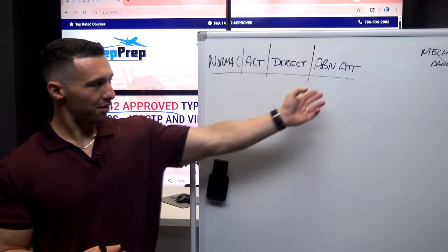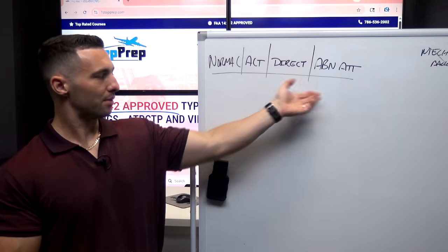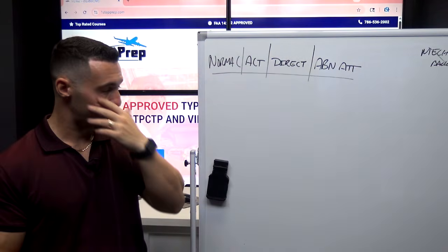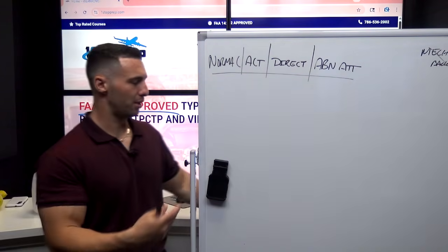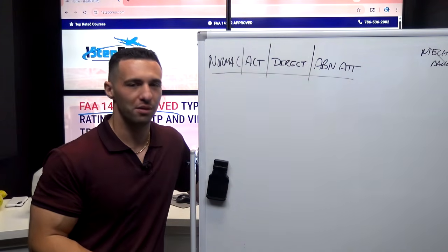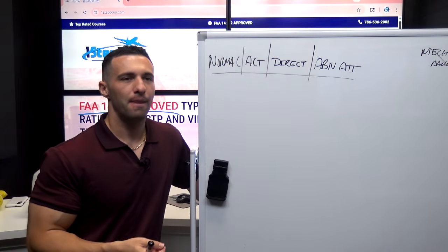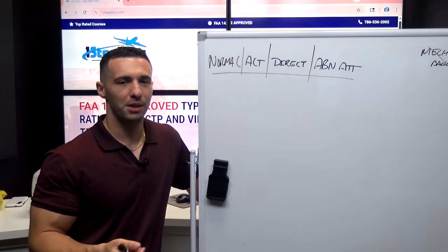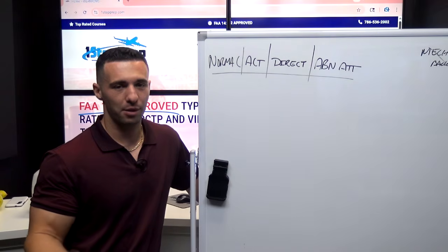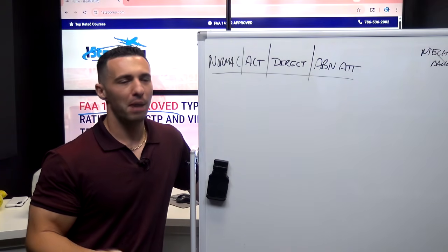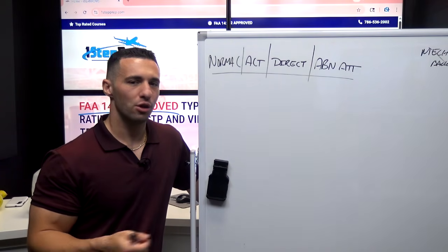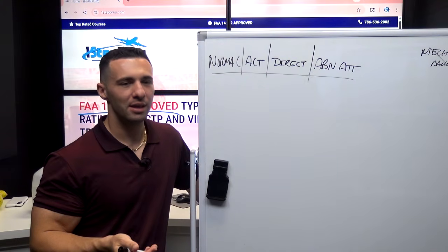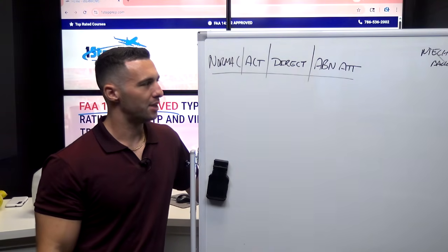This is one of these laws. Now, I guess a lot of these decayed or degraded laws, or maybe some that you'll never see in your career, hopefully, but certainly abnormal attitude is one of the ones that I would hope you don't see. It's one of these that you have to get there not by a pilot input, because you couldn't get there by pilot input. This is like a mountain wave or wind shear, wake turbulence, or something disrupts you quickly, and all of a sudden you're kind of left to command the jet.